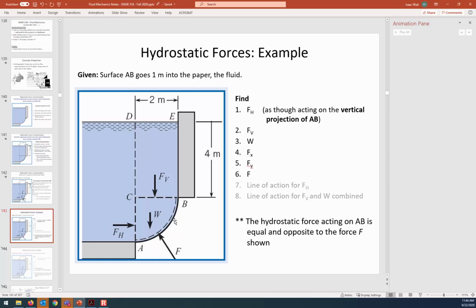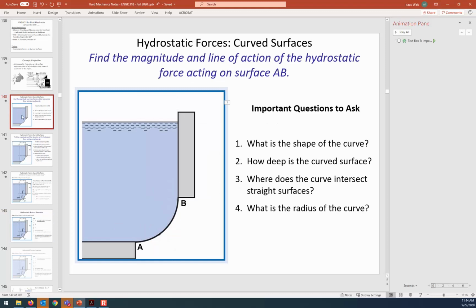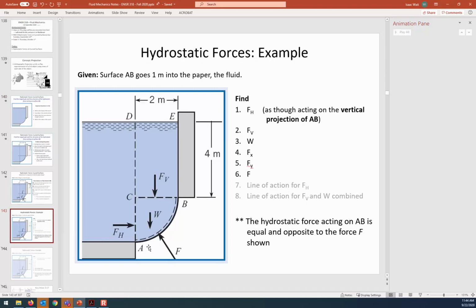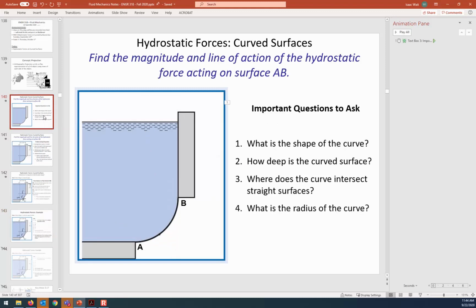And then the vertical forces we learned are just from the weight of the water. So you have to break up the overall shape. This is the original given sketch. It's maybe not originally given with these dashed lines. You have to fit the pieces together, or maybe break the pieces apart is a more accurate way to say it. You have to break the weight of the water above the gate into component pieces and then calculate, all right, what are the two different shapes that apply here.